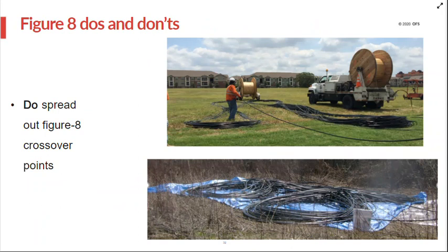And finally, in the bottom picture, you note that the cable is stored on a tarp. If you're in a muddy area, it's a good idea to use a tarp to keep the cable from picking up mud and debris, which will only make your installation more difficult. And also, if you're in an area where there's brush or twigs or sticks that may snag the cable, possibly kink the cable, it's always a good idea to lay a tarp down just to protect the cable.